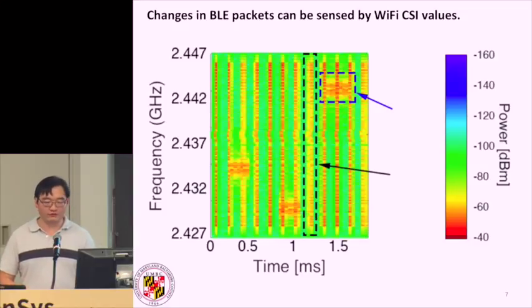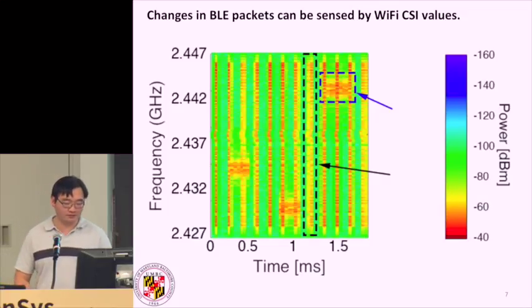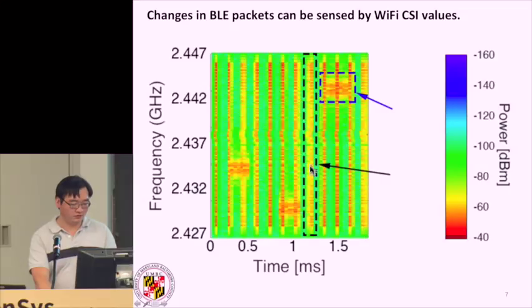So in this graph, this is the waterfall display of the spectrum over time. The y-axis, of course, is frequency. The x-axis is time. And you notice the wideband communication, which is this. And that, of course, is the standard Wi-Fi packets being transmitted.